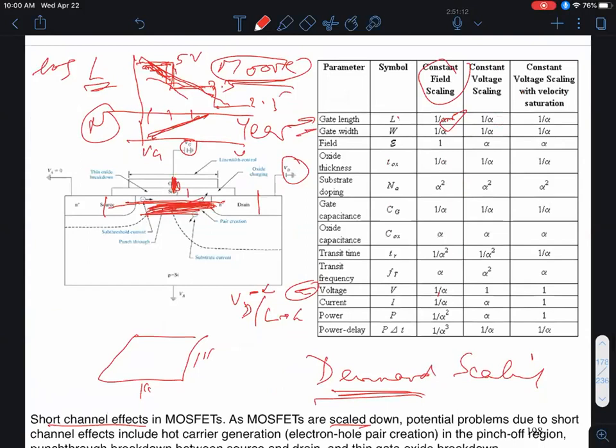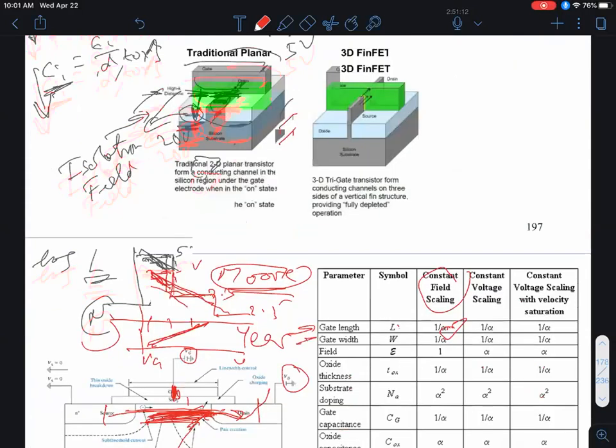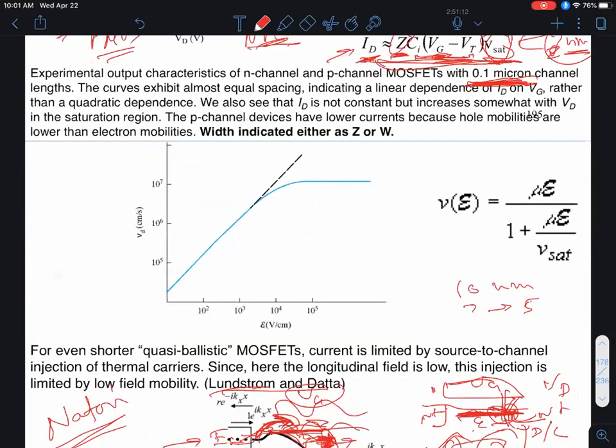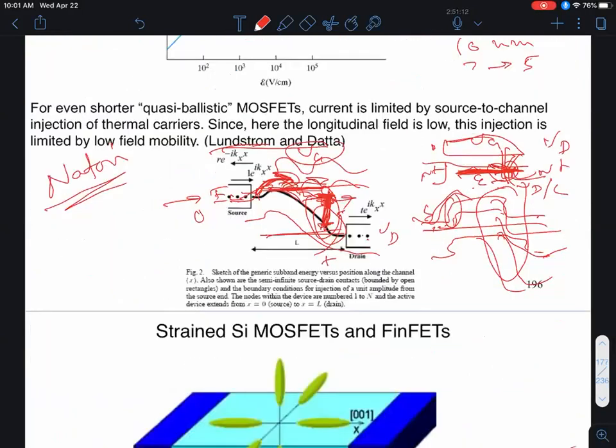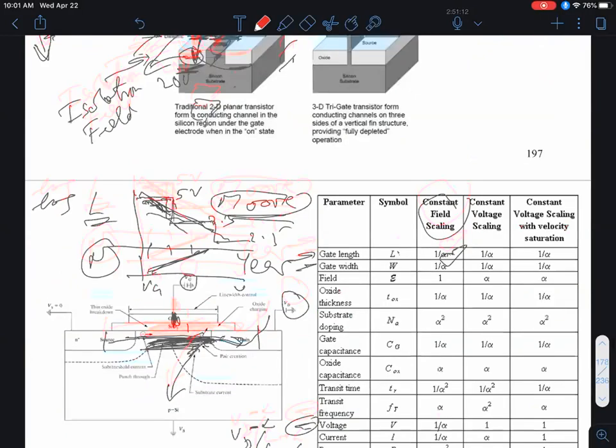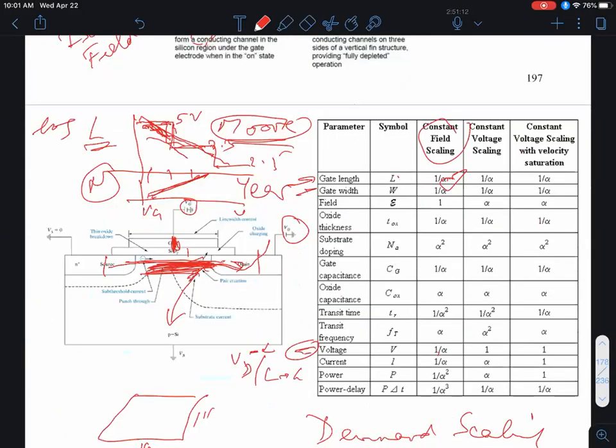So you can get electron-hole pair generation by impact ionization. The holes will travel towards the substrate, while the primary electron and the secondary electron go to the drain. As a result, the current will not saturate but go up. That's one reason for the increase of the drain current. There's a whole bunch of other bad effects that can happen. Carriers can be injected into the gate oxide, and some of them can be trapped as fixed oxide charges. That's an example of the hot electron damage that I mentioned in the last lecture. I'll elaborate on that again.